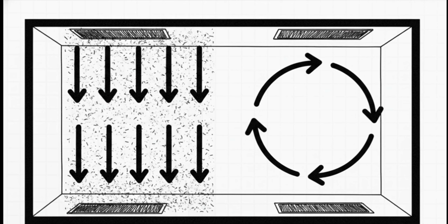But here's the thing. The architecture isn't just static walls and floors. It's also the dynamic movement of the air itself. The engineering guidelines specify a really precise air velocity, typically 0.45 meters per second, to maintain unidirectional airflow. This physically sweeps particles away from critical zones.